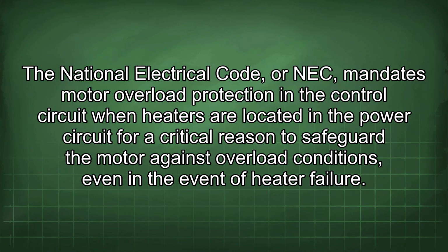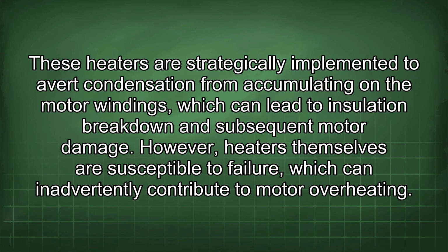The National Electrical Code, or NEC, mandates motor overload protection in the control circuit when heaters are located in the power circuit for a critical reason: to safeguard the motor against overload conditions, even in the event of heater failure. These heaters are strategically implemented to avert condensation from accumulating on the motor windings, which can lead to insulation breakdown and subsequent motor damage. However, heaters themselves are susceptible to failure, which can inadvertently contribute to motor overheating.